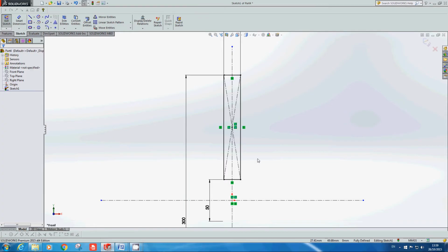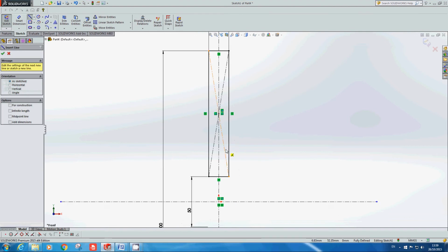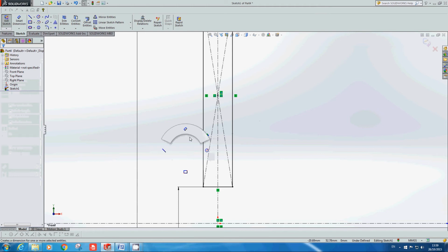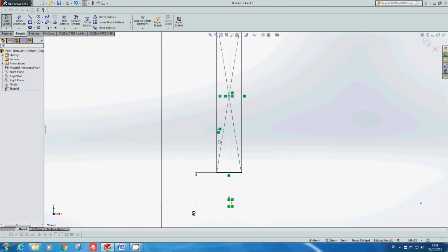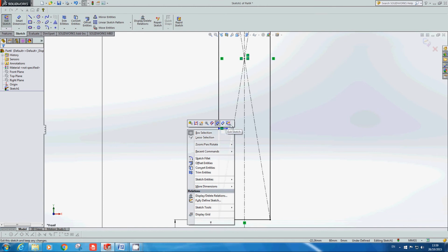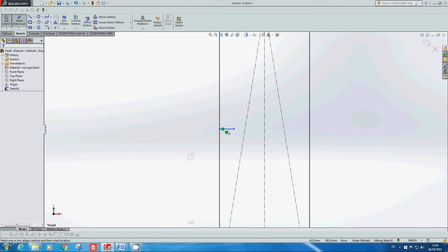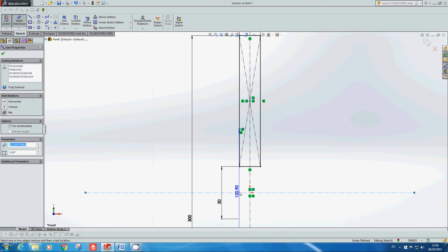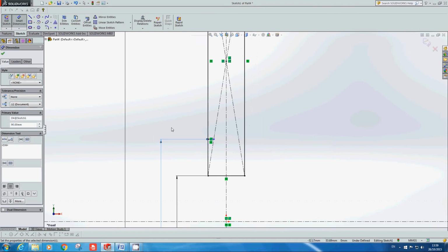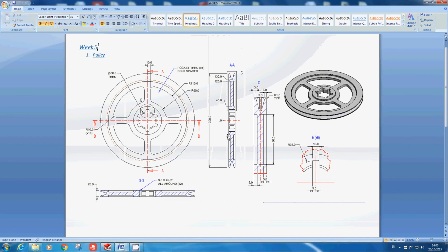So we'll go back in, click here, and I'm going to just draw that little line there. Not going to dimension or anything. I want to mention the length of it anyway, and that's from, again, I'm not in dimension, so I'll just click smart dimension and dimension that. Now you can leave it here at 45, or you can continue with the kind of center dimensions, and I'll put 90 here. Again, you can use 45 if you want. So that's that little section there. So just go back to the view again. So that little line is what I've just drawn.